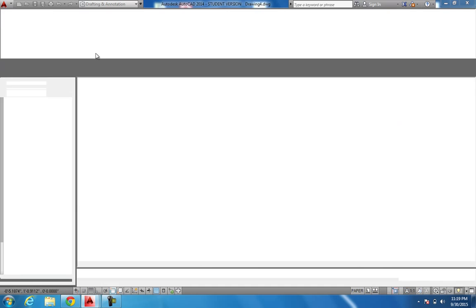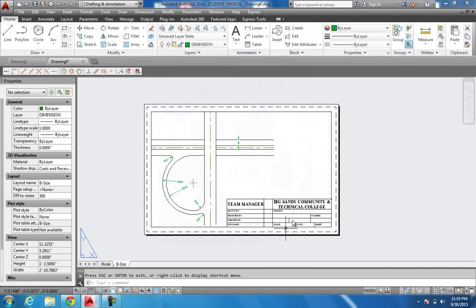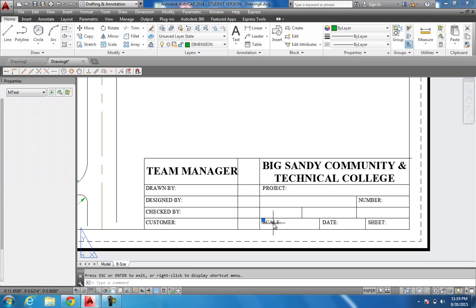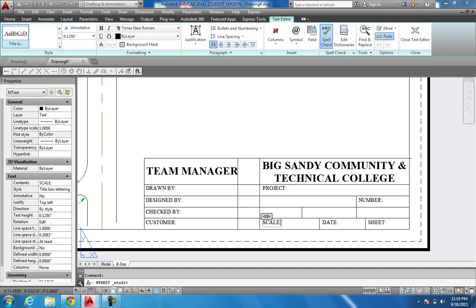before you print. And also make sure before you print that you fill out all of your data, and make sure it's in paper space when you do that, because this is where it's found. And all you have to do is, just like scale, double click it and come over here and just type it in. 1 inch equals 60 foot.